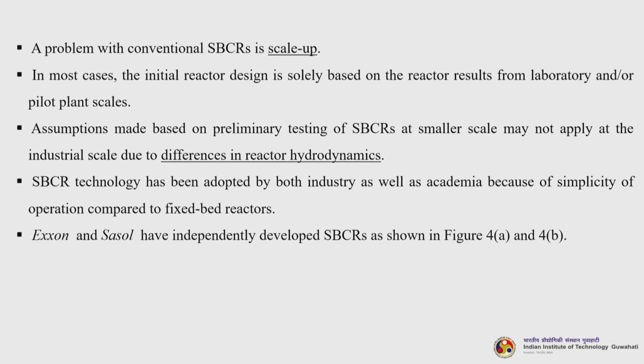A problem with the conventional SBCRs is the scale up. In most cases, the initial reactor design is solely based on the reactor results from laboratory and or pilot plant scale studies. Assumptions made based on preliminary testing of the slurry bubble column reactors at small scale may not apply at the industrial scale due to the differences in the reactor hydrodynamics.